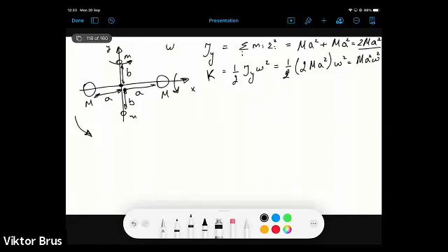If we consider rotation about axis x, then it will be an equivalent situation because these two bodies with mass capital M located on axis x will not contribute to the moment of inertia, since the distance to the axis of rotation for these bodies will be equal to 0. So instead of this capital M, we will put these smaller masses in order to get Ix.